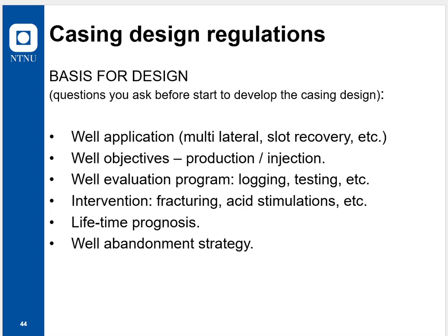We need to know also the parts from the subsurface department, anything that is related to formation, because when we do P&A, we make barriers that are completely going from competent formation over to good steel and solid internal plugs, like a full barrier.